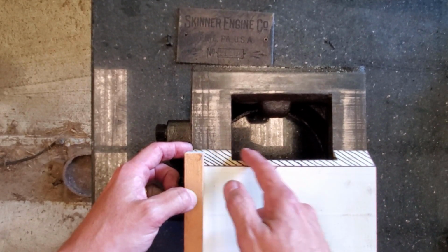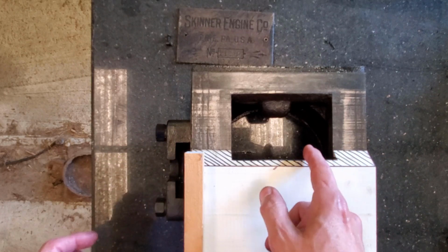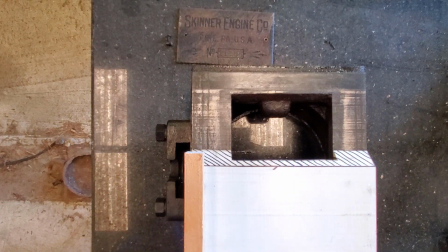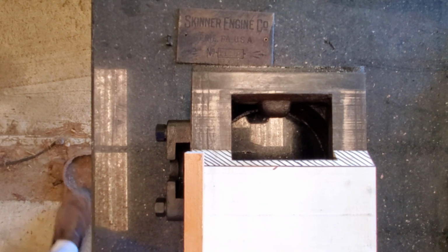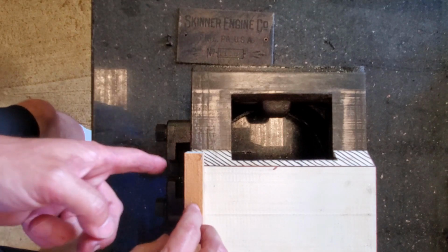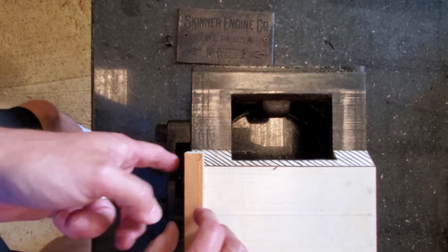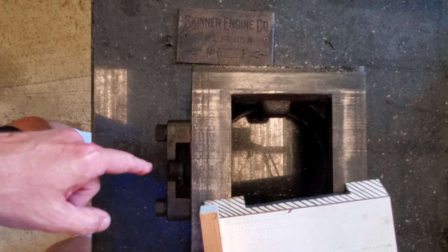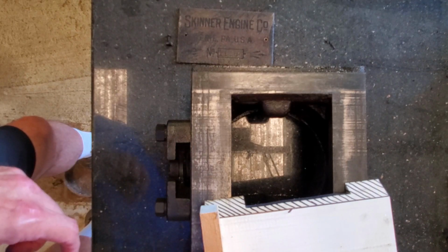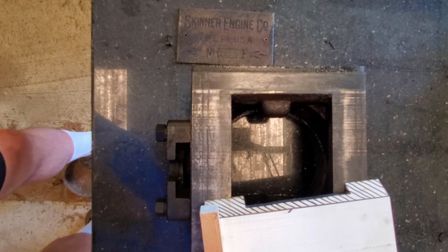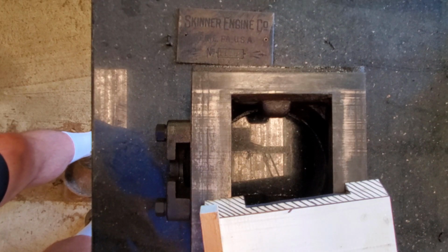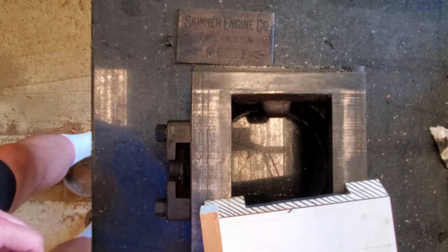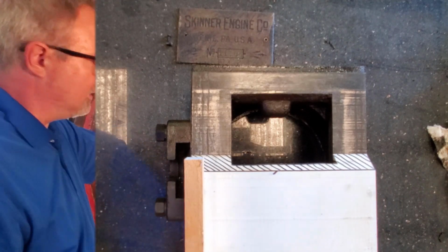And where I've cut this out, pretend that's going to give us access from the pressure ports on either side of the cylinder to the exhaust port on the steam chest. And then this back face is exactly on a plane with this cavity, which traps the end of the slide valve actuator. So I'm going to put this on the engine and you can see a little bit better what it's going to tell us.